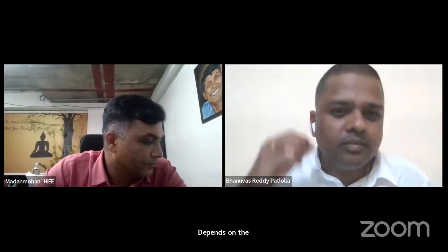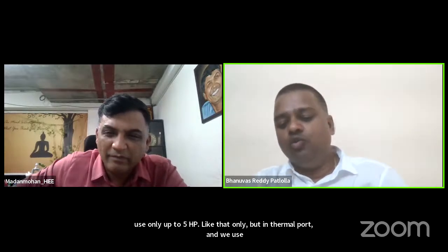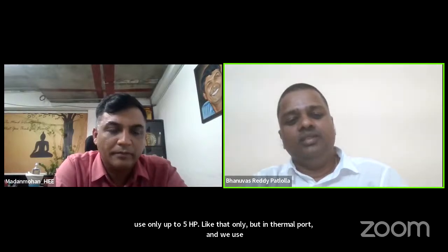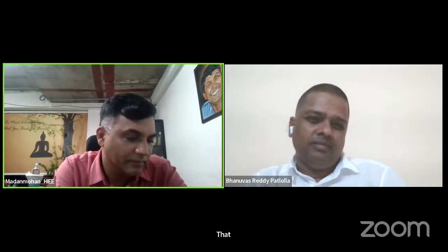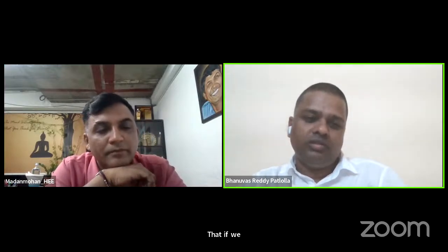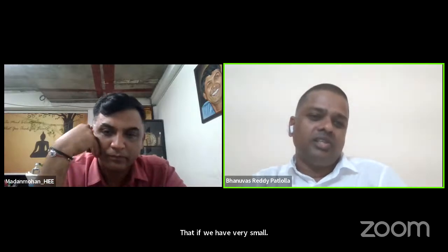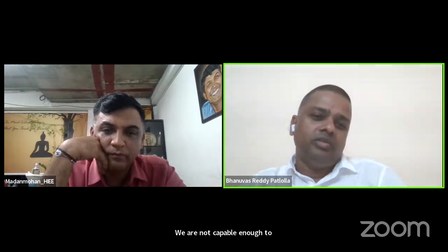Depends on the application, sir, normally we use DOL only up to 5 HP like that. No, sir, but in thermal power plant, no, you cannot say that one. It depends on how much capacity of source we have. It's not a standard that for very small motors we use DOL. If we have a very small source and we are not capable enough to give the starting current, then we will go for a star delta starter to reduce the starting current.